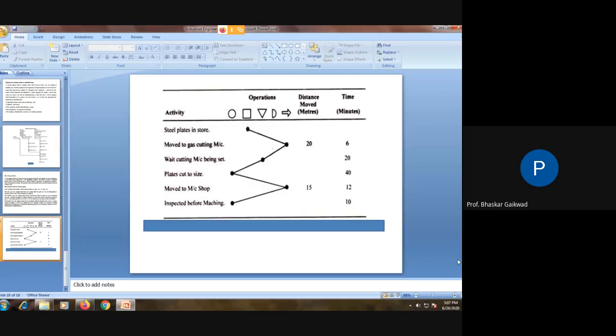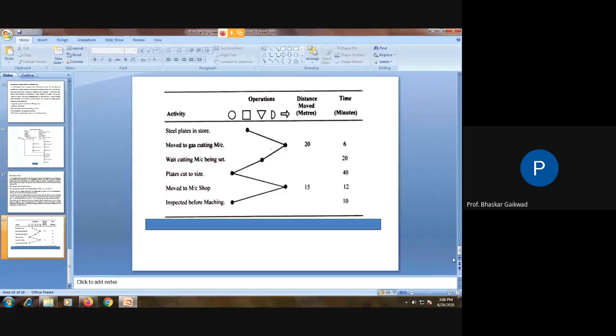So if you manufacture the washer at a time, means both operations combined, blanking and piercing combined operation, within one stroke it is possible to manufacture the washers. So one operation we can remove. If you go to industry, some industries still manufacture washers with piercing operation different and blanking operation different. So if you go for method study, we can combine this piercing and blanking operation.